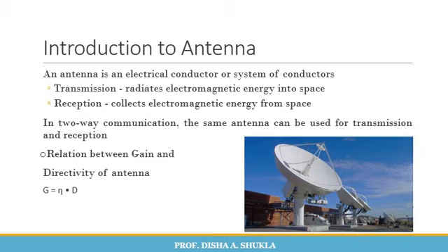We see the phenomenon of increased directivity when comparing a light bulb to a spotlight. Whenever you are using a light bulb or a spotlight, the amount of light that you get differs. For example, a 100-watt spotlight will provide more light in a particular direction than a 100-watt light bulb, and less light in another direction. We can say that the spotlight has more directivity than the light bulb. The spotlight is comparable to an antenna with increased directivity.